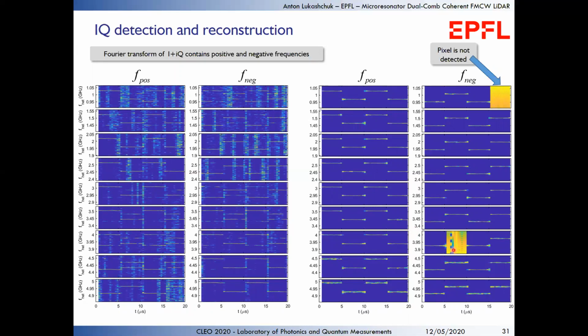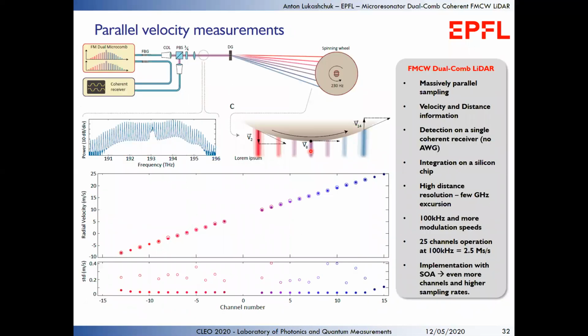So, I mean, it happens that we cannot determine the signal here, or here we also had some problem with the image and signal. And then we performed again a mock-up measurement. We determined the velocity profile of this rotating wheel, a flywheel, a simple toy car motor. And again, we were able to measure those velocities. And so on, filled circles correspond to 1 period measurement time, and unfilled circles correspond to 10 periods measurement time, because for some measurements, as I have already said, the signal couldn't be measured due to the lack of SNR, because we have some limited amplification bandwidth of our amplifier.